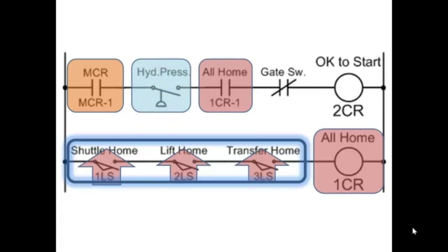So at some point, that normally open switch is now going to close because that switch has an operator inside of the hydraulic system, and the pressure pushes it closed against spring tension. That spring tension is adjustable, very much like the regulator that we showed you in another lecture on basic electricity and magnetism. So the master control relay is reset, so it's safe to start.